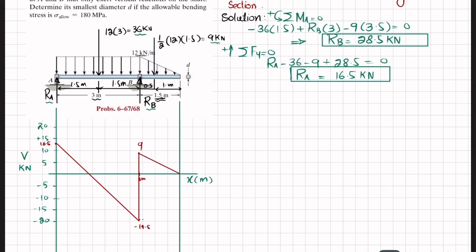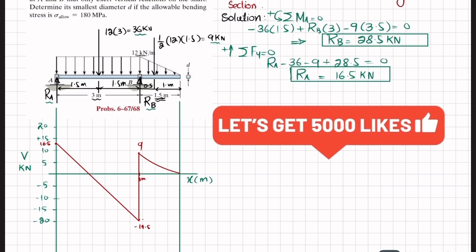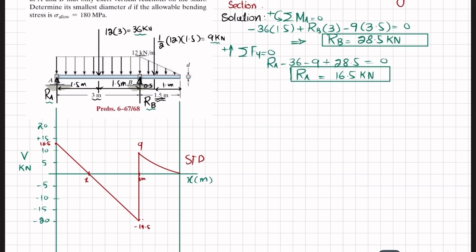It will be like a curve, not a straight line. So this will be your shear force diagram. Now at this point you can see the shear force is 0, and at this point the bending moment will be maximum. So for that we will find this x.